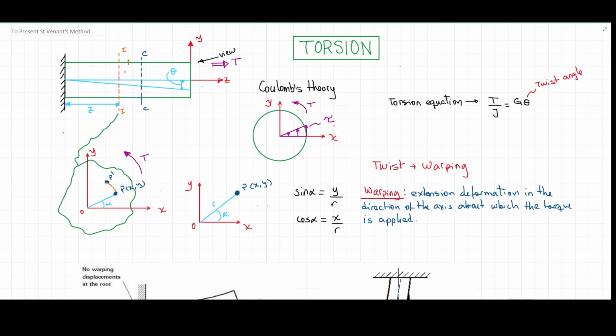So that's something that might be happening there, and that's why Saint Venant takes care of that, and that's why we are taking a look at that in this course, even though it's in a very simplified way. Because when you either continue your studies or work with these types of elements, non-symmetrical elements, you're going to say, well, the normal theory does not apply here. I need to apply a different one. Questions so far?